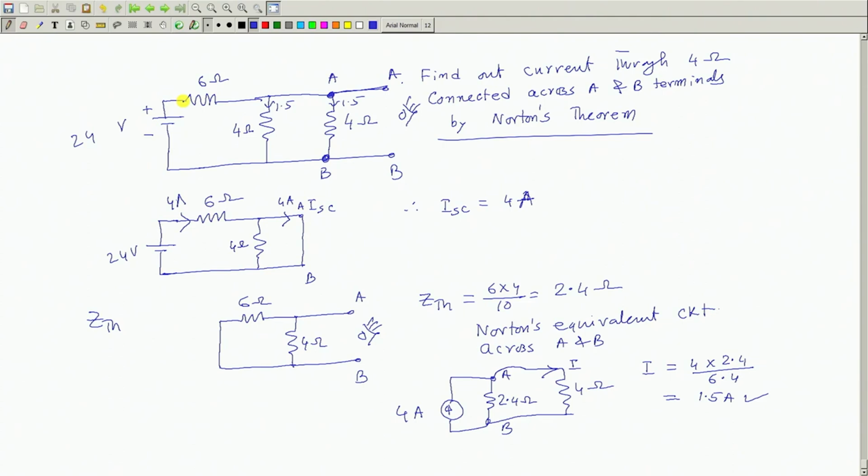So, this is how Norton's theorem can be applied. It is a very interesting statement because networks may be very complicated. Across a pair of points, any 2 points you take tapping from the network, the theorem tells that behind all these things you can always think there is a current source in parallel with some impedance, which happens to be Z Thevenin's. We call it Z Thevenin's, and then your AB terminal. So, complexity of the left hand side goes.